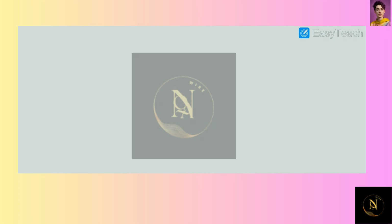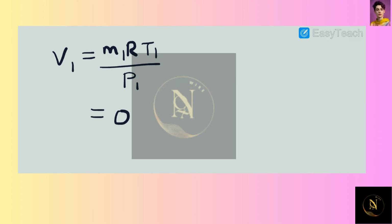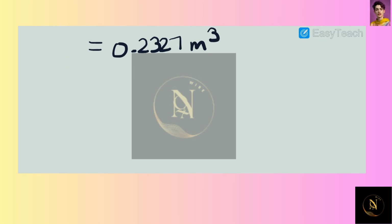Next, we're going to use the ideal gas law to solve for our initial and final volumes. Our initial volume will be equal to M1 R T1 all over P1. And this gives us an initial volume equal to 0.2327 cubic meters. Now, given in the problem statement that the final volume is 80% of the initial volume, we can say that V2 is equal to 0.8 V1, which gives us a final volume equal to 0.1862 cubic meters.